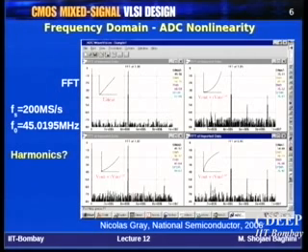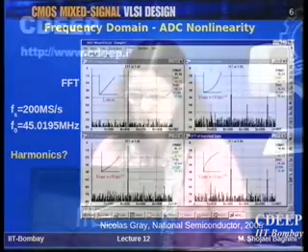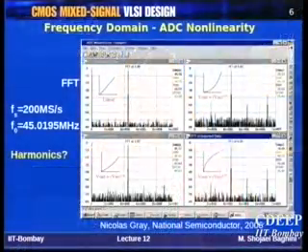So in any FFT spectrum, these are of course harmonics, as you can see, and these are exactly at those frequencies, the example frequencies that we have calculated now. You can cross check it. For example, this is 45, you can see. This will be that 64 something we had, 64.9. This should be that 90.039. And then eventually it shows how these values change. So therefore, noise floor still is around minus 70 dB, but harmonics now are higher. Okay, any question? Okay, so this was the first concept of nonlinearity.